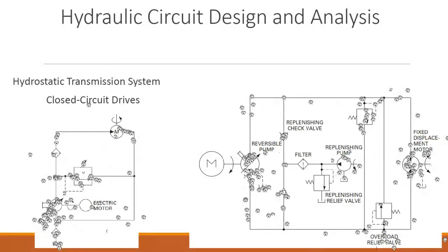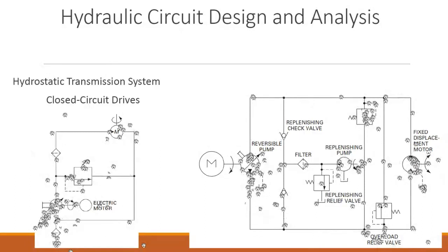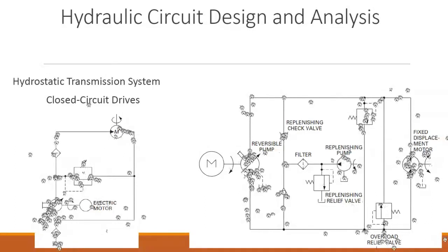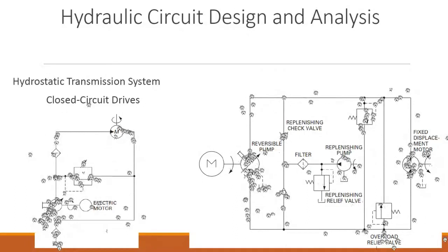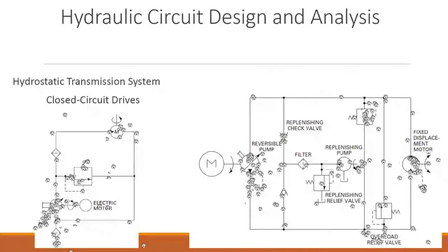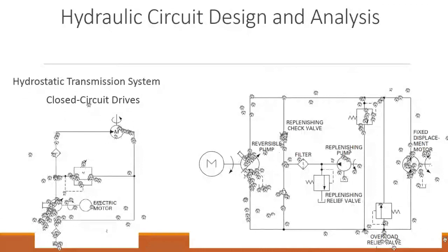Now when it comes here, we see what is the direction of the flow of hydraulic oil. If it is like this, and the oil is less, in that case it will come here, but it will not go from here, because now this is the high pressure side, and this is the low pressure side. When it comes here, because it is the high pressure side, it is being pushed against the seat, or against the poppet or opening, so it will not open from here.